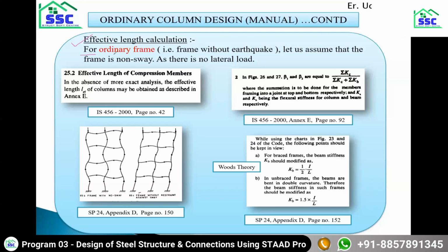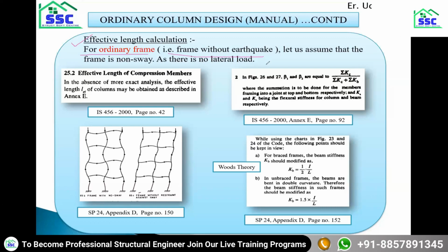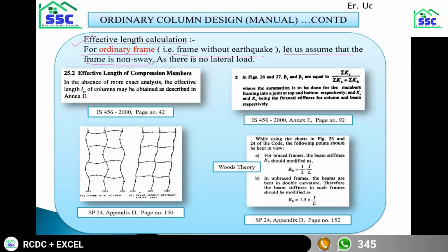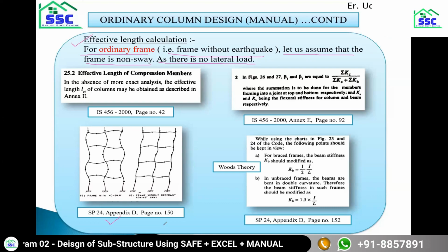Now, for an ordinary frame, that is a frame without earthquake, let us assume that the frame is non-sway. There is no sway in my frame. I'm just assuming it, because there are no lateral loads in my model. If you go to SP24 Appendix D on page number 150, they have given a very nice diagram of what we mean by a non-sway frame and a sway frame.